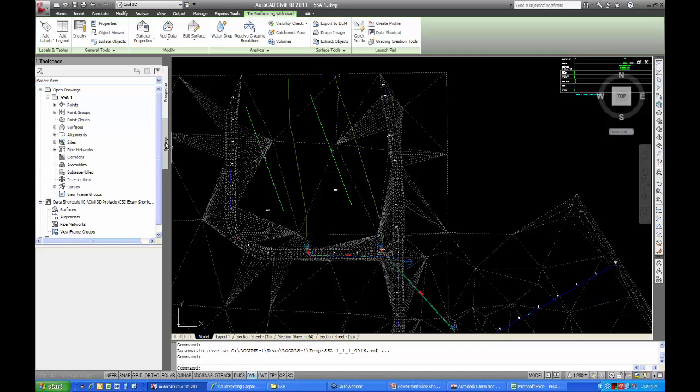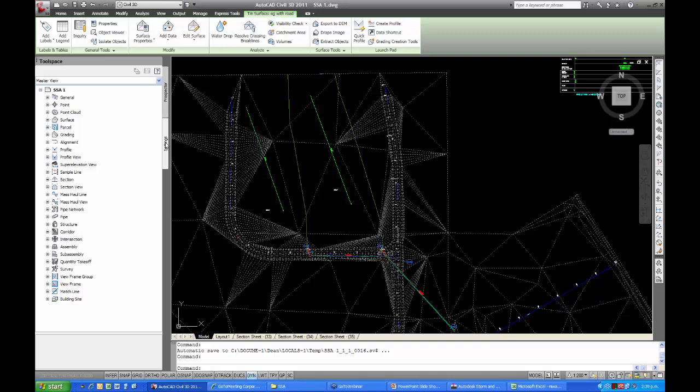It's coming through slowly. Go to the Settings tab in Civil 3D to get into the styles, of course. There we go, you should see Civil 3D up there now. Go to Pipe Networks, into my parts list, the ANZ parts list. I can go and edit it.